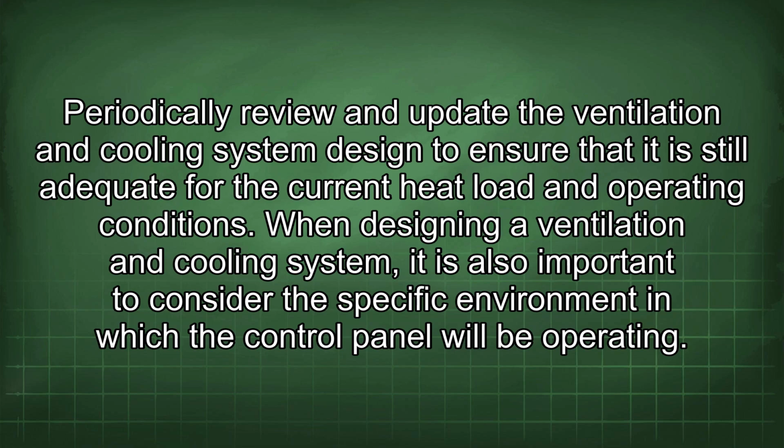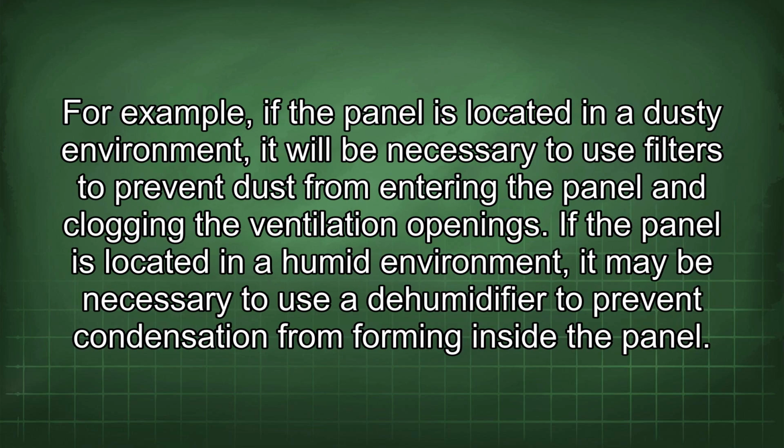When designing a ventilation and cooling system, it is also important to consider the specific environment in which the control panel will be operating. For example, if the panel is located in a dusty environment, it will be necessary to use filters to prevent dust from entering the panel and clogging the ventilation openings. If the panel is located in a humid environment, it may be necessary to use a dehumidifier to prevent condensation from forming inside the panel.